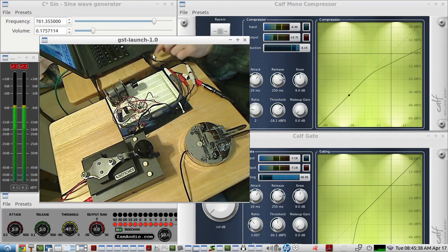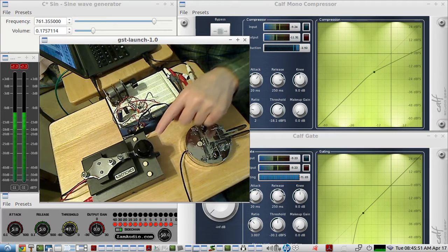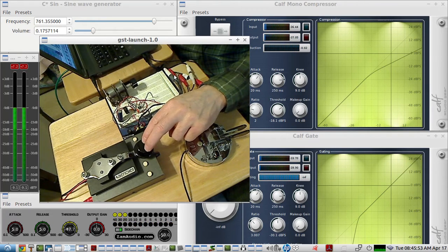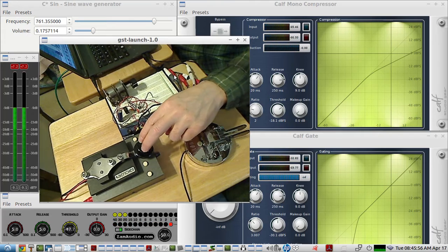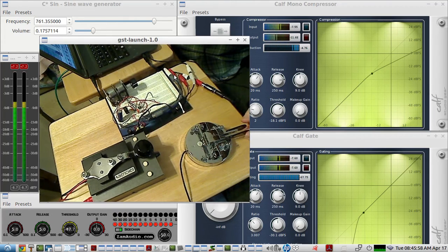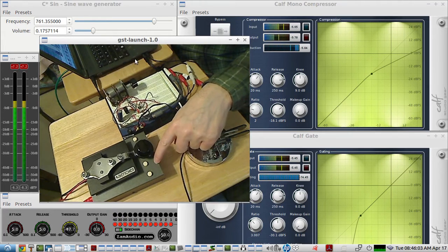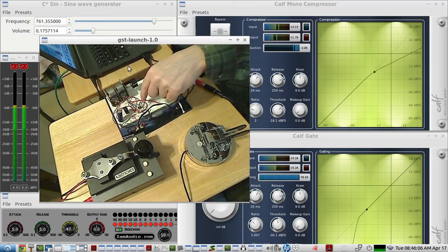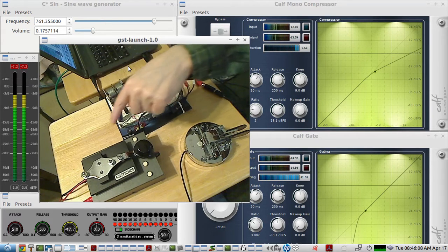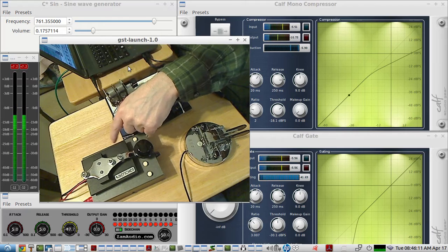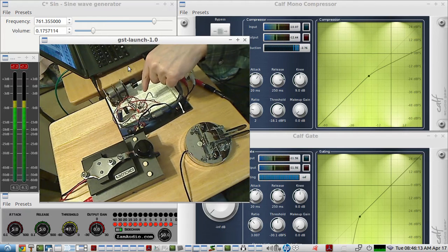Right now on the laptop, we have the headphone jack right here, but over here is the microphone jack, and we bring out a splitter. So we have both left and right channels. On the left channel, we have Morse code, which is going to the straight key and the pedals. It's coming out of this keyer here, and it's keying a 555 chip, just like you would a rig. So we're using the rig keying jack on the keyer here, and that's what keys the 555.